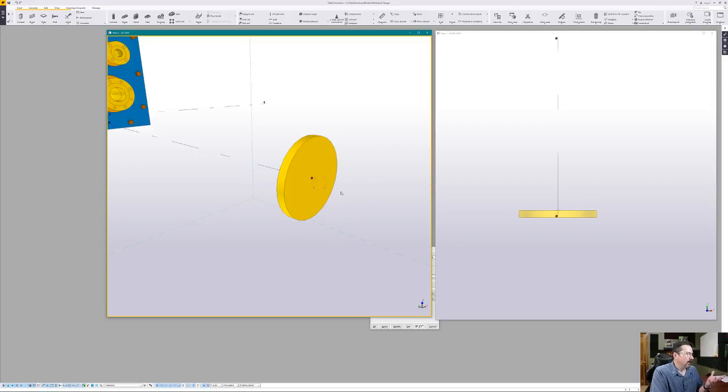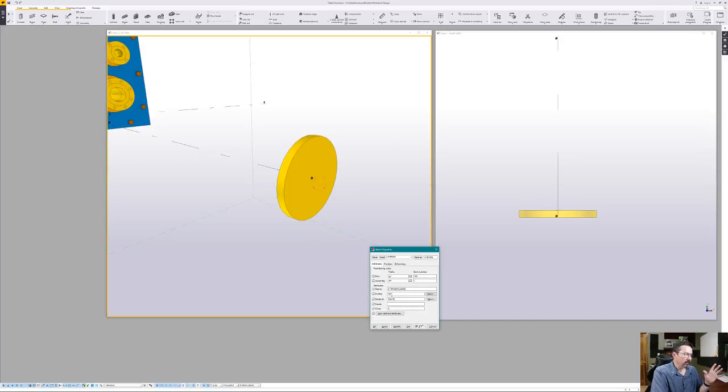While I've got this all set up, this is the only piece that I'm really concerned about having all of the information from the user-defined attributes and all of the things that we had defined in the beam itself, the part prefix, the part start number, the name, all of that other stuff. I want that set to this because this is going to be the main part. Everything else is kind of inconsequential.